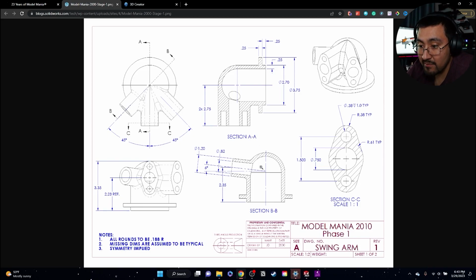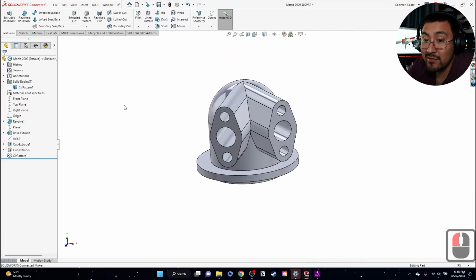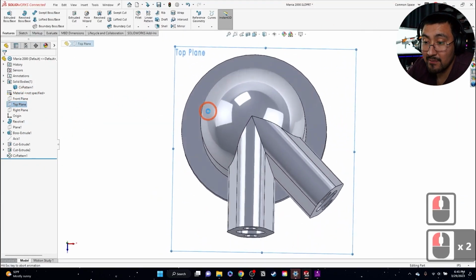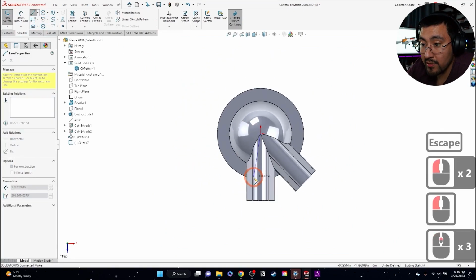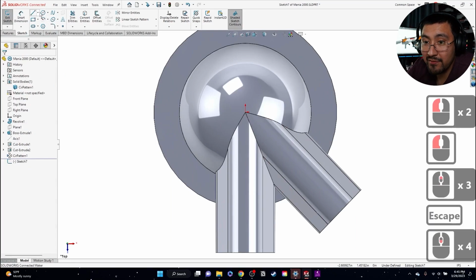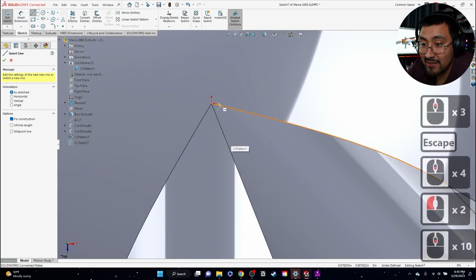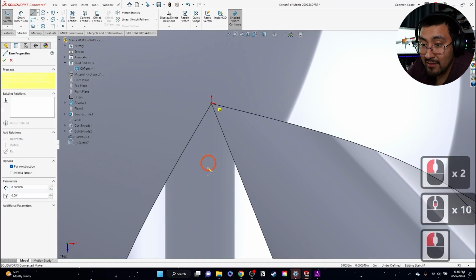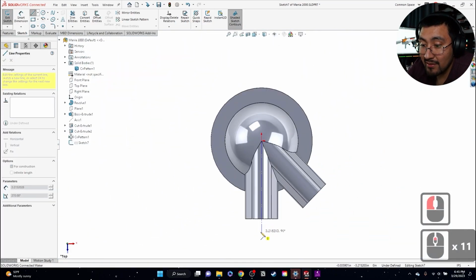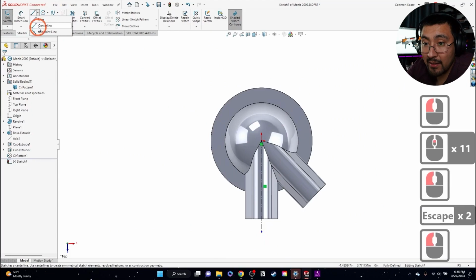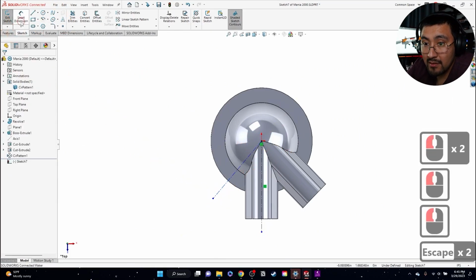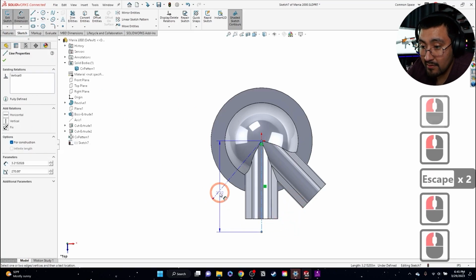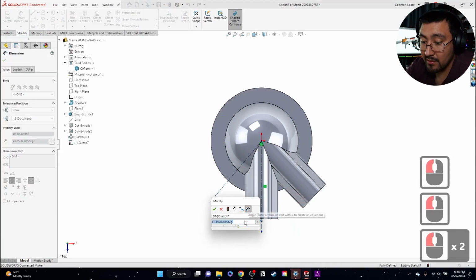They give us the section BB at 6 degrees. So I'm gonna do the sketch method. It's gonna take 2 sketches though. So I'm gonna go sketch here. We'll draw one. Oops. We'll make sure you grab the origin on this one. So it looks like these are a little weird here. Grab that, and I'm gonna make a line that's 45 degrees out. So smart dimension here to here. I'm gonna go 45 degrees out.